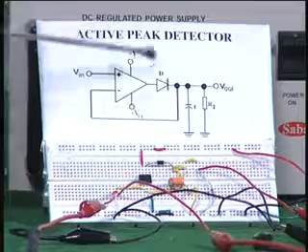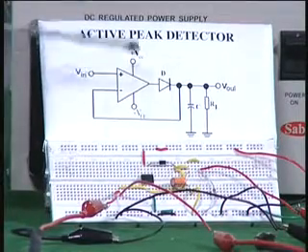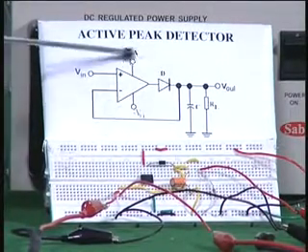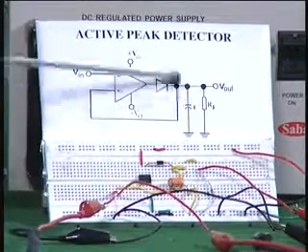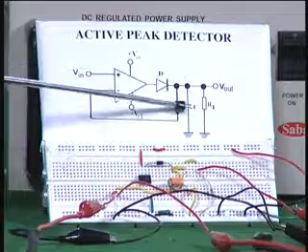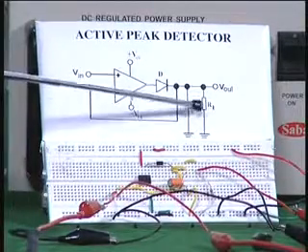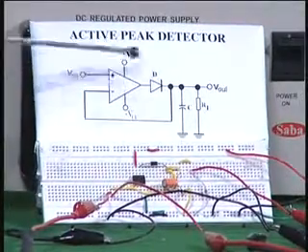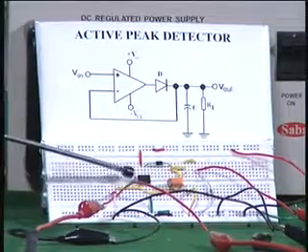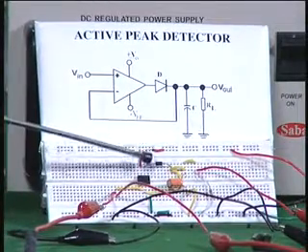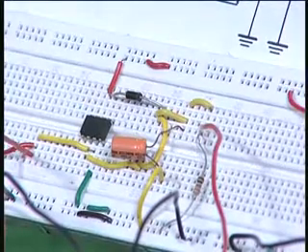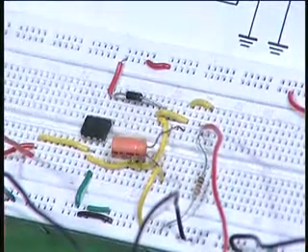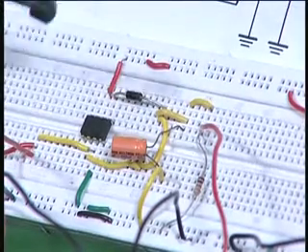Here you can see the same circuit, which is a peak detector. You have the precision rectifier here with the diode and the op amp, and you have a capacitor here connected for peak detection, and this is RL, the load resistor. The corresponding circuit is shown here. You can again see the operational amplifier, you can see the normal diode, and I have put about 100 microfarad capacitor in place of this, and I have RL which is around 10K here.